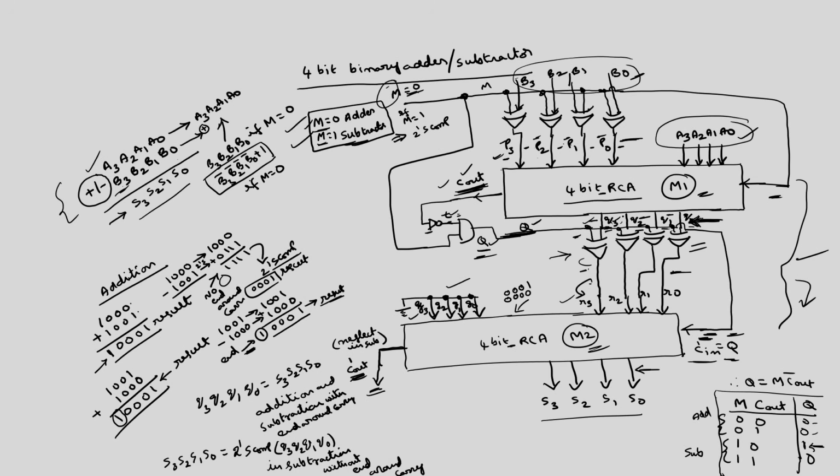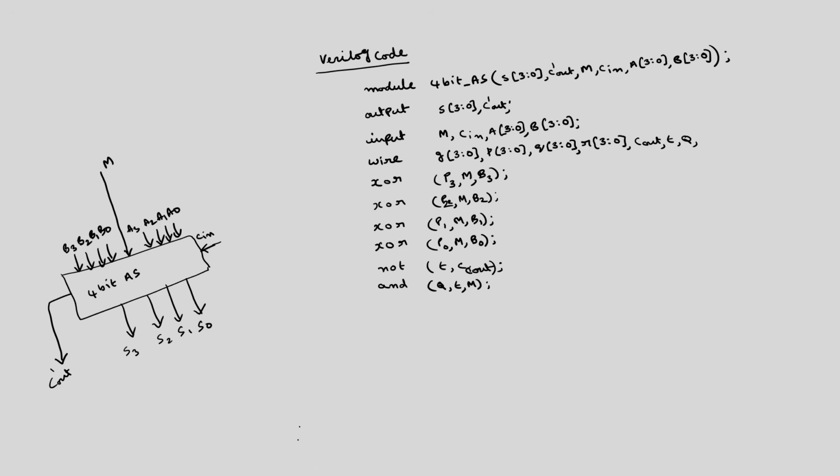What else? I have generated these Qs, then I have to generate Rs by exclusive OR with Q and small q's. R3, R2, R1, R0. Exclusive OR, R3 is the output, Q is one input, exclusive OR with Q3.